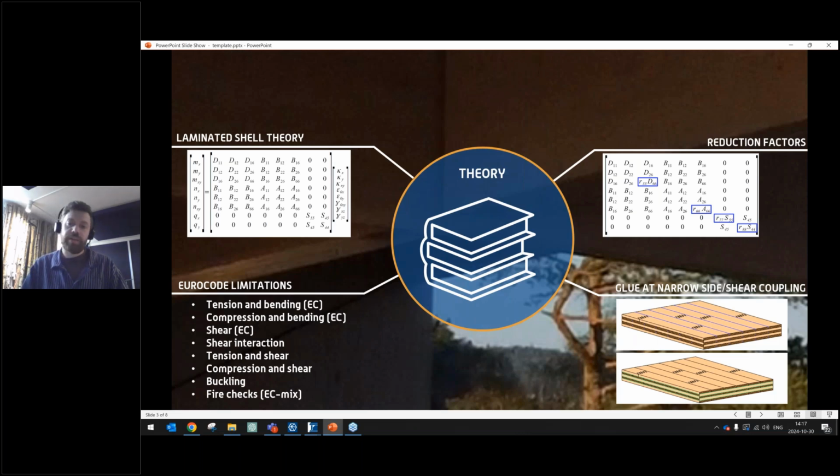The other setting that's important to take into consideration is the shear coupling between the different layers. And this is normally always the case that this should be on. That's indicated in the bottom picture here. You can see some green highlights here in between each layer. That's basically if you have glued together different layers. Otherwise, there will be no interaction between each layer.